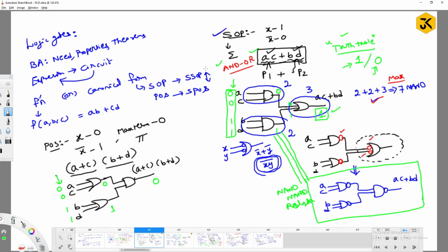In order to convert an AND-OR gate to NAND-NAND realization, the simple solution is to put a complement on the AND gates' output and a complement on the OR gate's inputs, and then replace the OR with the complemented inputs by a NAND gate.